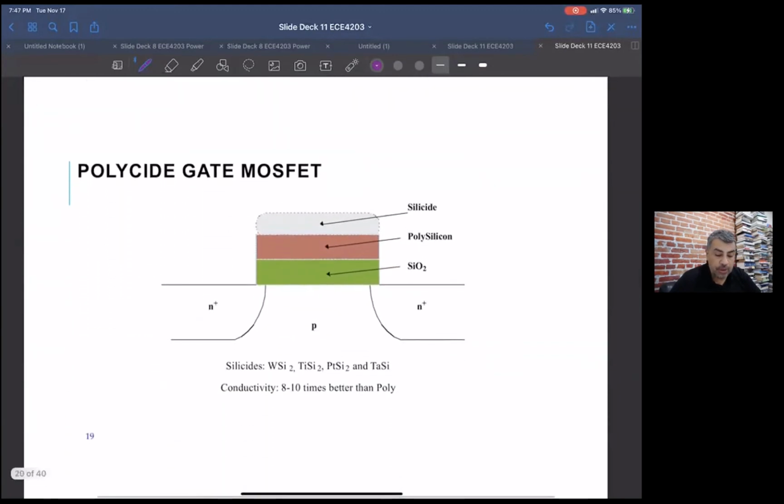Another thing about foundries, you can reduce the resistance of gates. It's not so bad when you have small gates, but if you have long gates, polysilicon resistance can be pretty high on the gates. So they have these things called silicide that reduces the resistance of poly. I wouldn't use poly for very long routing wires, but you can use it for very short routing, say when you're connecting the N and the P transistors of a gate.